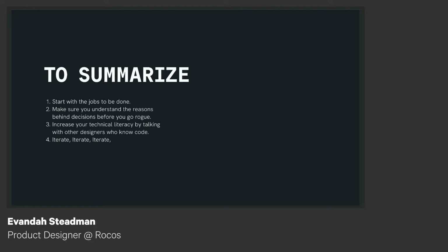In principle, you could, but you start running up against the limit, which is how quickly the light will saturate the scene, how quickly the camera will capture the data, and then when the light turns off, it will desaturate the scene, ready for the next light to saturate from a different direction. You inherently have the cycle of the LEDs warming up and cooling off again. If you're too quick, they pollute each other as they go around. They don't quite finish before the next one kicks in. So you're restricted to about half a frame a second if you do it right.